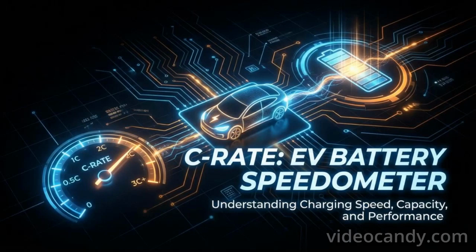C rate is the ratio of charge or discharge current to battery capacity, acting as a universal speedometer for energy flow. 1C fills or empties a pack in 1 hour, 0.5C in 2 hours, 2C in 30 minutes, and 3C in 20 minutes. This dimensionless figure lets engineers, drivers, and fleet managers instantly compare charging speed, acceleration punch, and thermal load across any EV chemistry or size without decoding ampere or kilowatt figures.